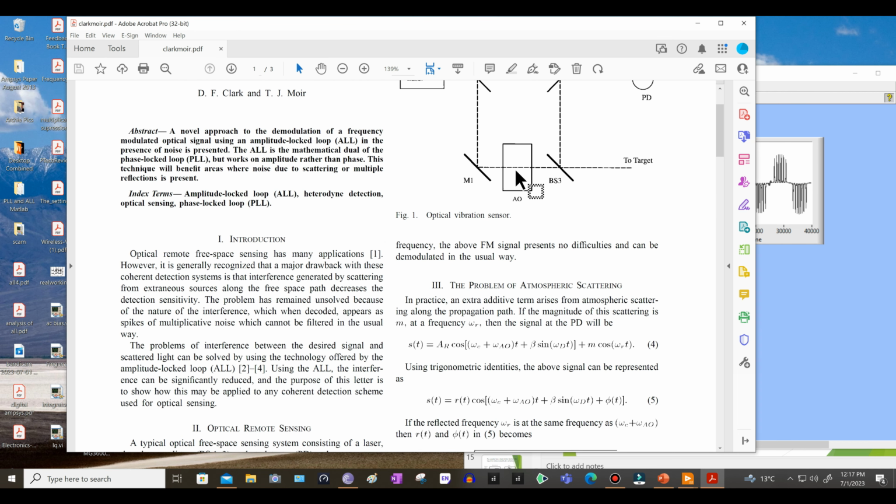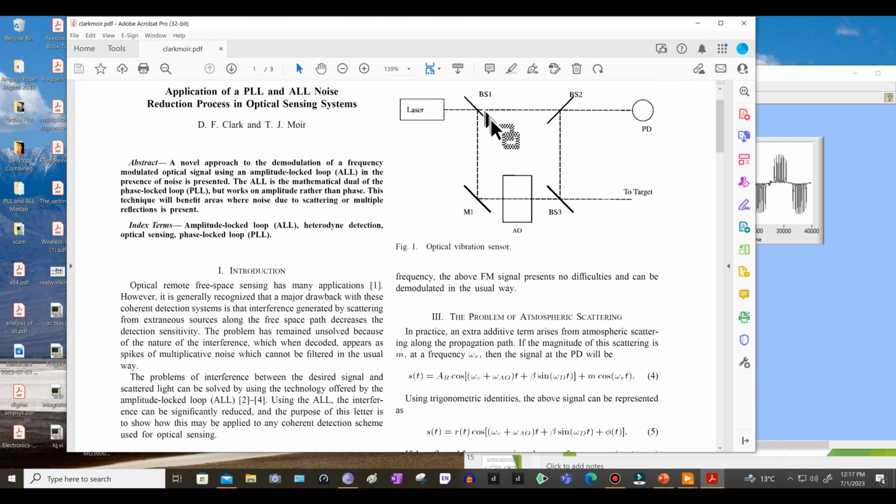What it does is it gives you a signal out, which is basically FM, because the laser fires at its target, and the frequency of the target changes the laser by tiny amounts, and those tiny amounts can be picked up by the interferometer. This acousto-optic modulator, also called a Bragg cell, I believe, gives out 100 megahertz, like an IF signal, like FM basically at 100 megahertz.